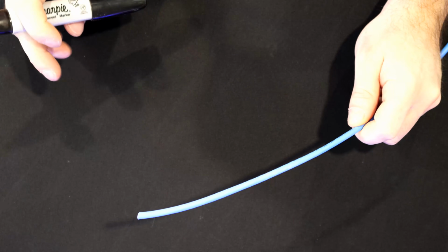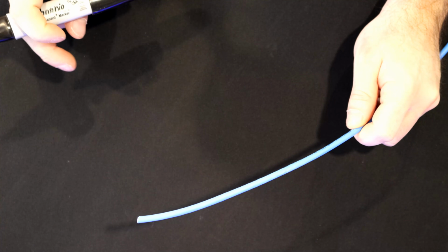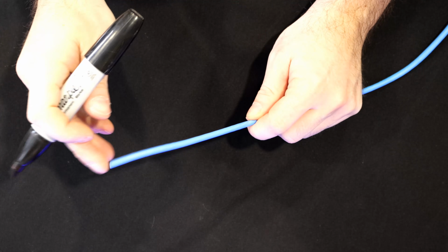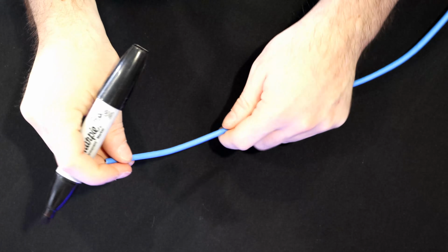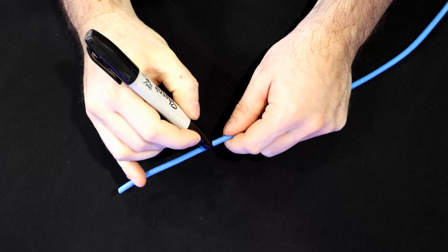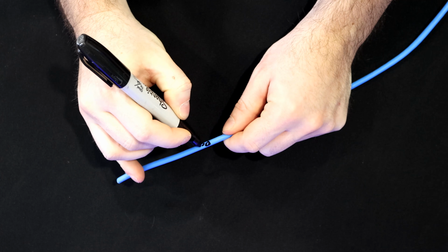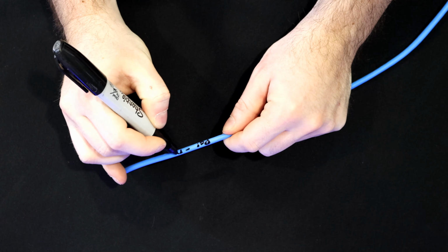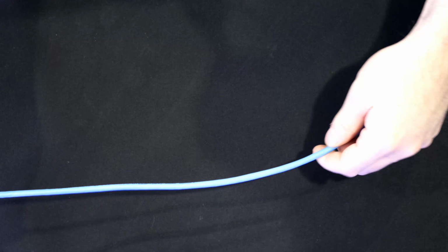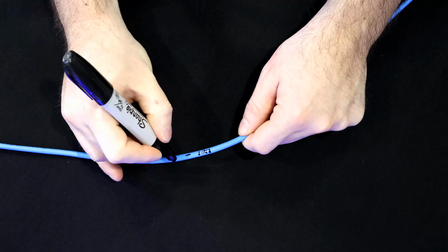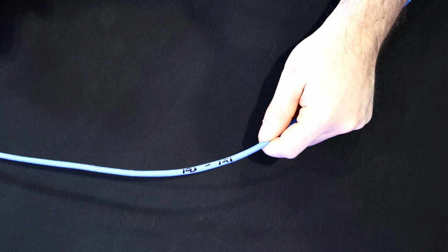When our cabling is coming out of our box, we would mark the box with the cable number. Then we would also grab the cable and mark it as well. So we'll say this one is D01. We just grab our Sharpie and mark it D01. We'd write it a couple times. We'd also move down the cable, maybe about a foot, and mark it again. That way, if some of the markings rub off when we're pulling it, we have it marked in multiple different areas.